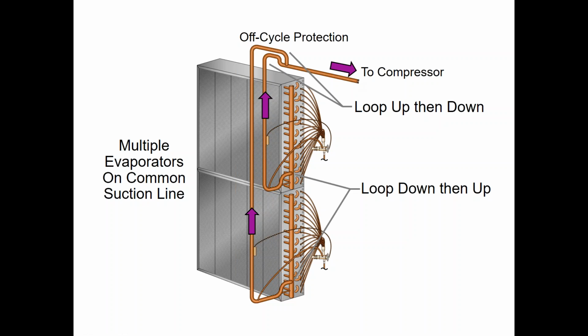Okay. As we get into the piping in a little bit with double suction risers, we talk about an A pipe, we'll talk about a B pipe, and we talk about a C pipe. Your C pipe is always the main suction pipe run back. That will always be your C dimension. When we get into double suction risers, there's going to be an A pipe dimension and a B pipe dimension. When we get to those slides, I'll get that clarified. Okay.